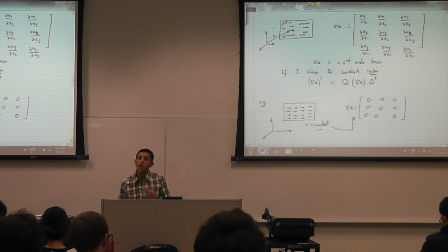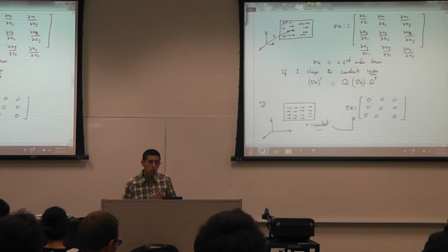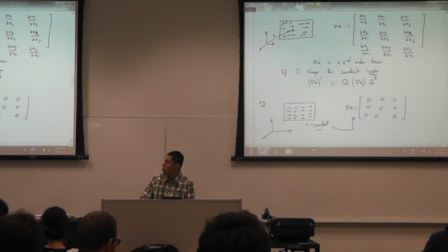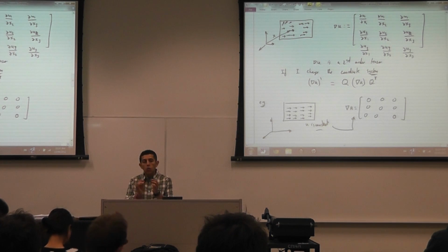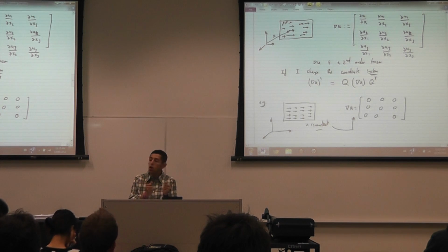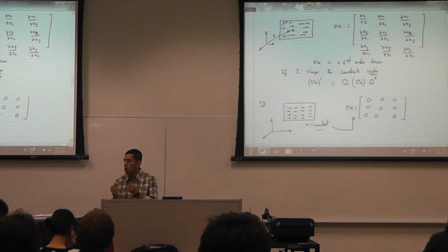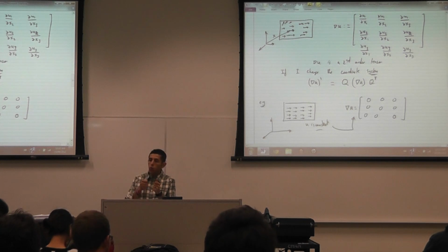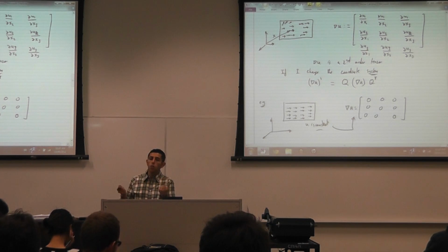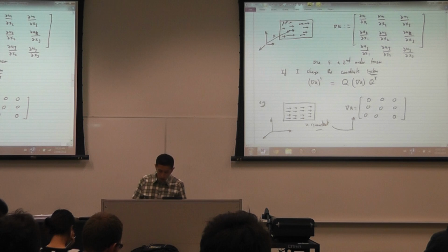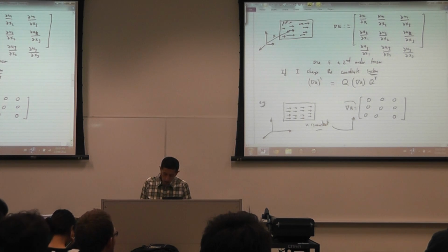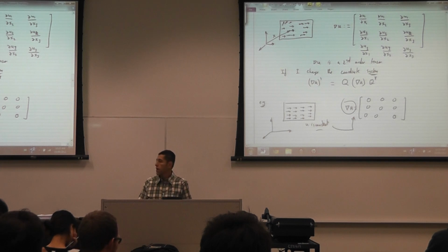The strain, when we discuss the strain in chapter 3, will be derived from this matrix, the gradient of u. I expect that I only see strain when points start moving with respect to each other, not as they all move together with the same displacement. You only see strain when one point moves more than the one before it, when the gradient of u starts having non-zero entries.